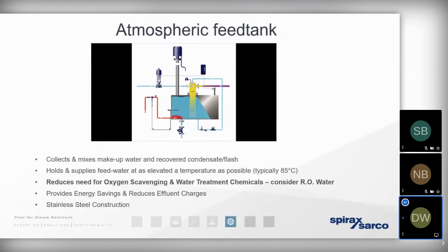First of all, if we've got hot water going into the boiler, we get less thermal fatigue, less shock, less wear and tear on the boiler. Hot water going into the boiler, we're going to respond and produce steam more rapidly whenever there's a demand. Hot water going into the boiler, we need to consume less fuel to raise steam again. But as far as steam condition or steam quality is concerned, there's another key benefit.